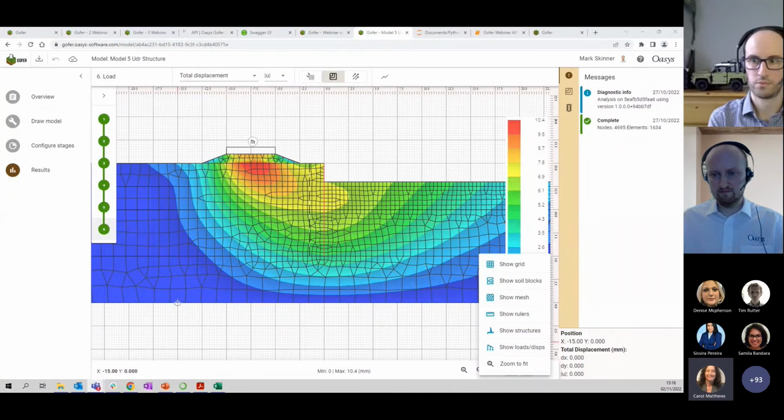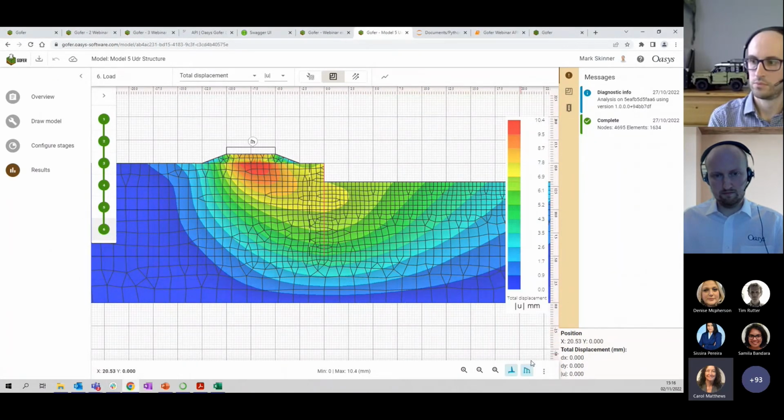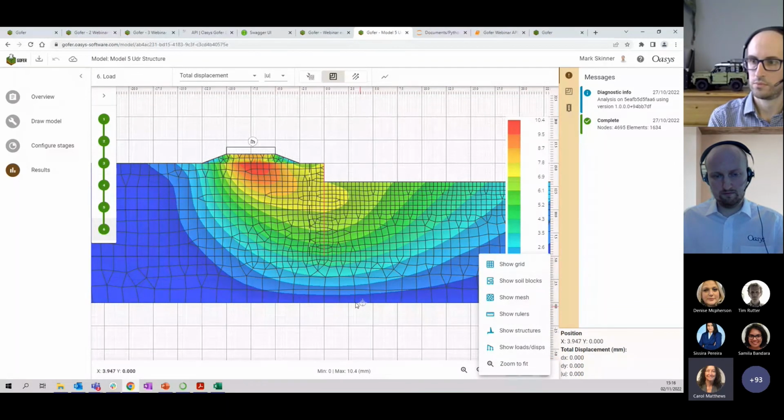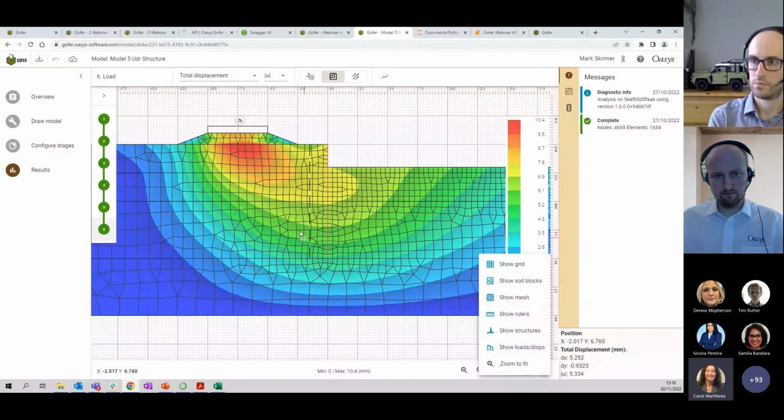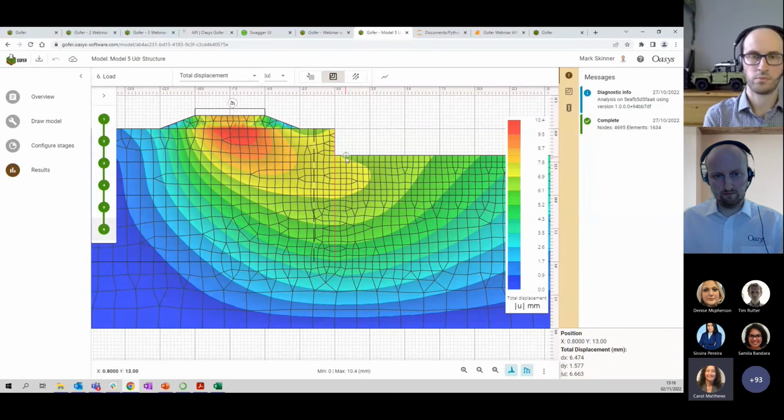We don't currently have mesh quality checks, but as you can see, we've used this mesher for a long time in a number of our programs. It's a third-party product and it's mixed quad and tri meshing. So the quads are 8-noded quads and the triangles are 6-noded triangles, so they have mid-side nodes.